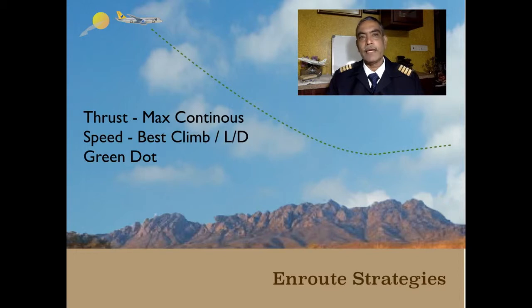With an engine failure, the pilot, after securing the engine, will change over to max continuous thrust, get onto a prescribed speed depending on the route, and then drift down to the drift down altitude or en route net, gross or net, which we shall see. So he would be drifting down to an appropriate altitude. That's the point which at this point we need to understand.